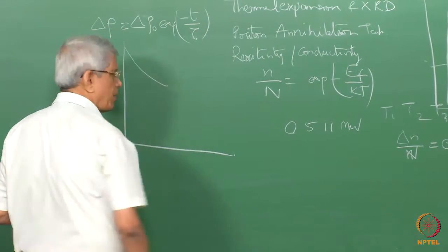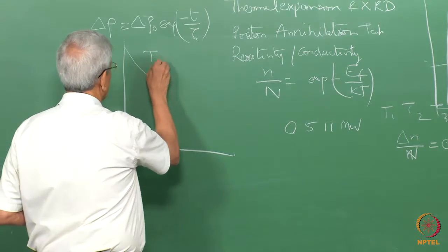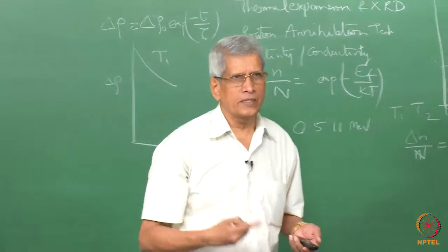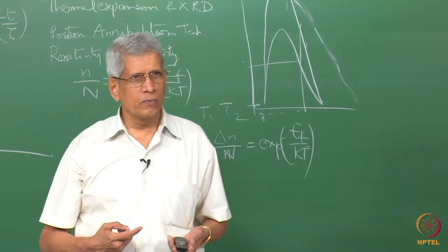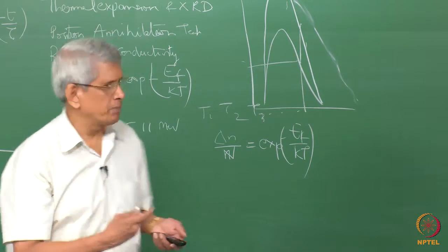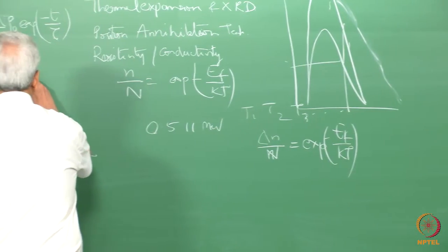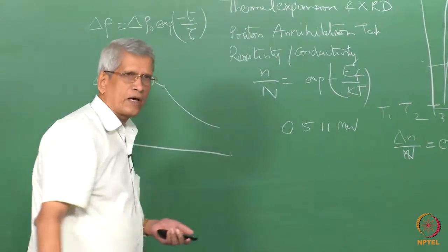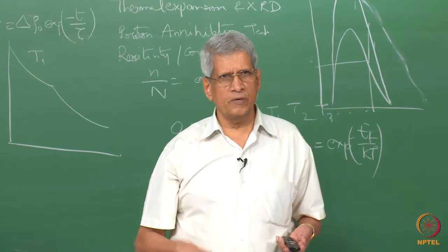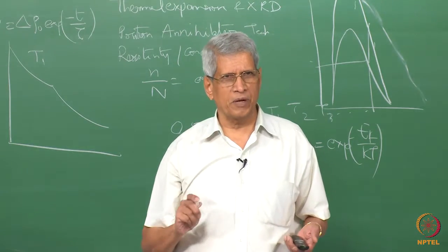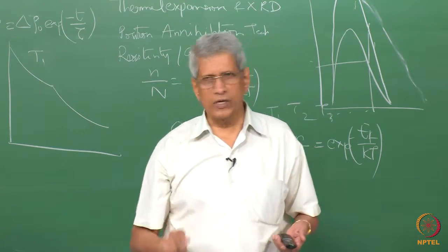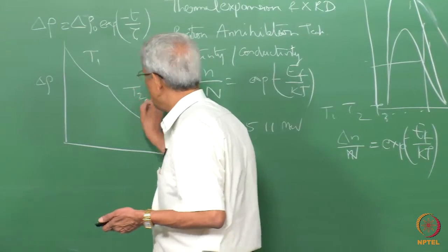Now this is done at a temperature T1. If I raise or lower the temperature, the relaxation time will be different because the rate at which the atoms jump changes. So I will get another plot corresponding to it, correct? We do this experiment for different annealing times; this is an isothermal experiment because all annealing is carried out at one particular temperature, this is T1, this is T2.